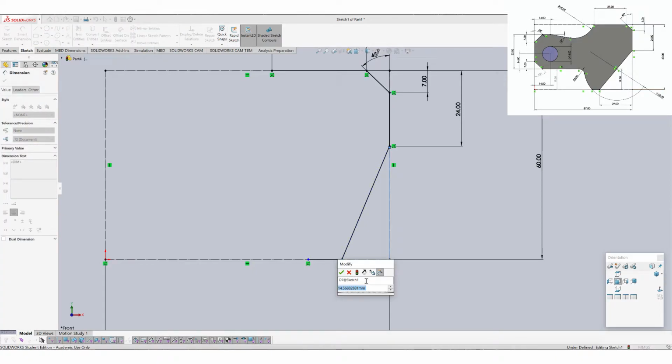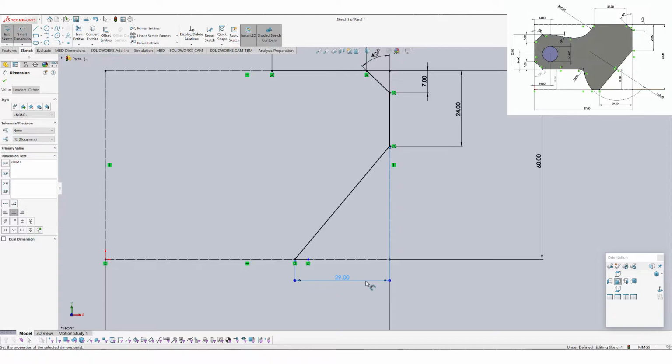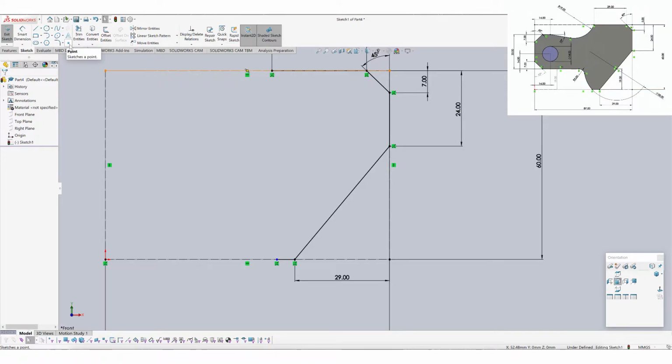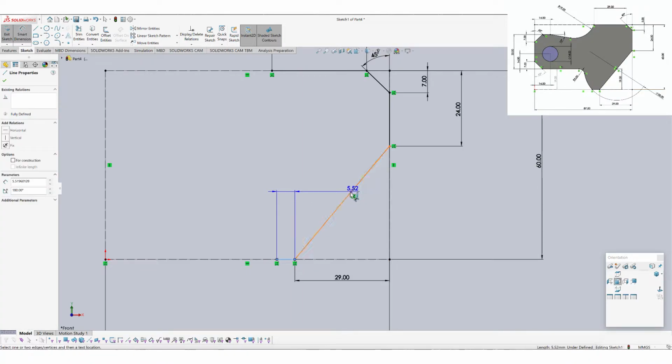So when setting up the diagonal line segment to 29 millimeters, notice the horizontal line at the bottom kind of flips sides. So it's really easy, just grab the point and move it back over to the correct position to move forward. Here I'm selecting a point as a reference, and I don't want that point to sit on or intersect another point because it'll get locked in position, so I moved it slightly above that center point on the diagonal line.